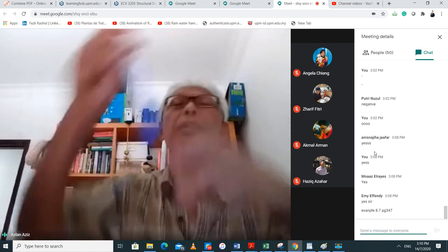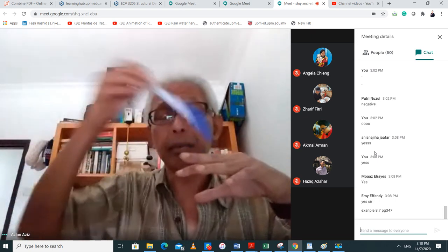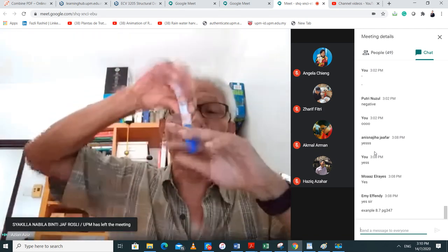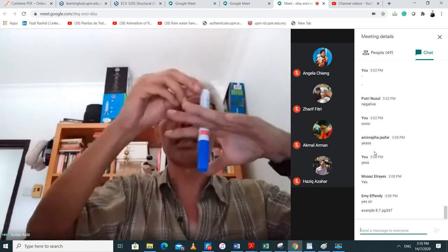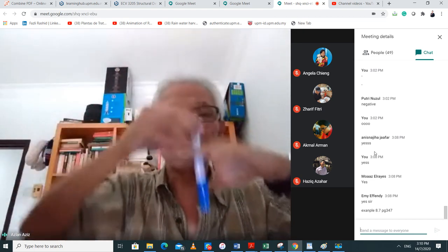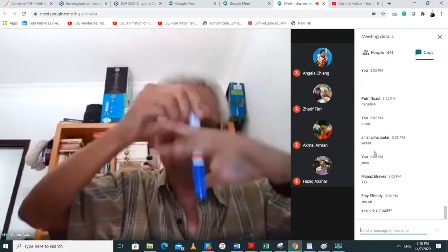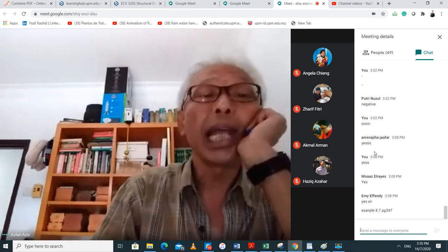Remind ourselves, SPT: you drill a hole, then you take out all that bit that drilled the hole, then you put your SPT inside the rod. You go down there, you go bang, bang, bang, bang at 1.5 meter. Then you take it out, you advance the hole, then you put the SPT again, you put it in at 3 meter, bang, bang, bang, bang. Okay? All right.